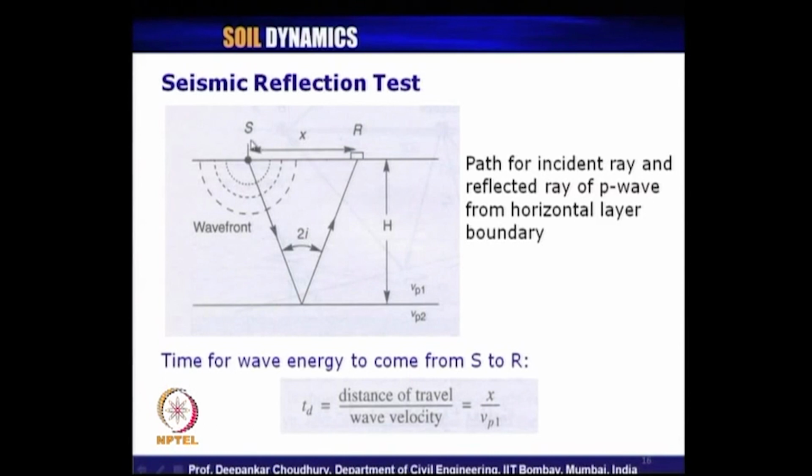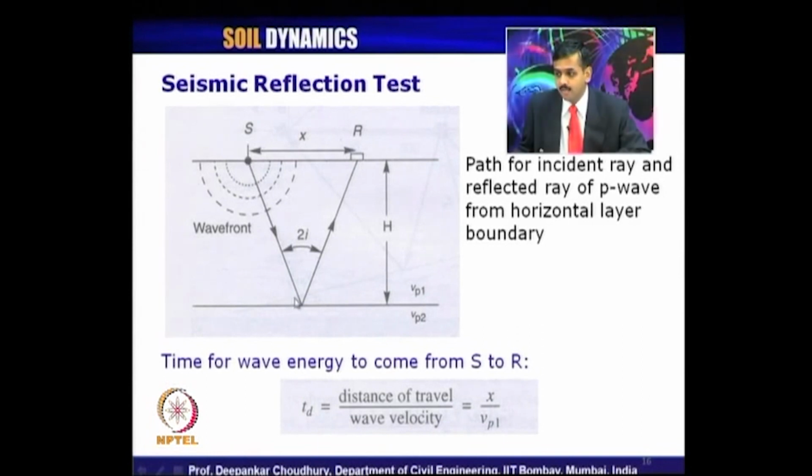This S is nothing but source, that is where you are creating that disturbance or vibration in the soil by using any of the above three methods, just now what we have described. And the point R is called receiver. So, these are receiving the disturbance created at this point, followed as waves through the soil media, and which is finally recorded at the receiver R.